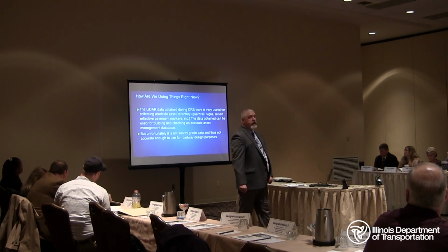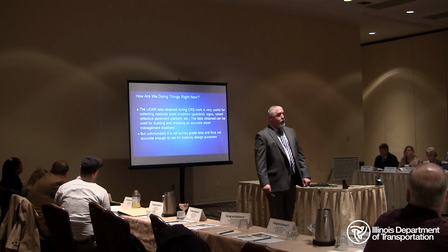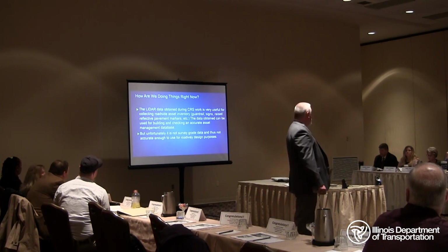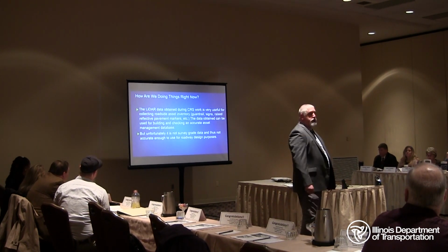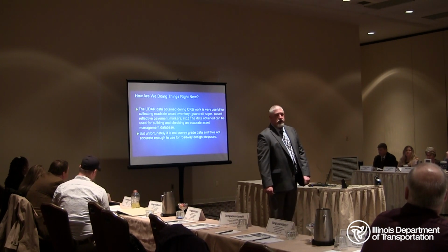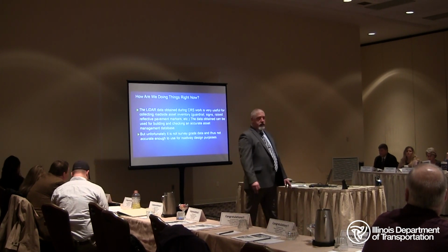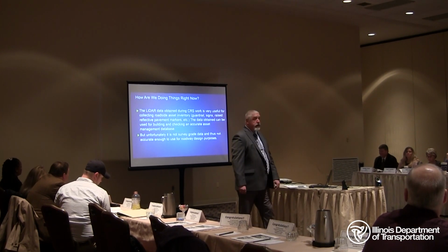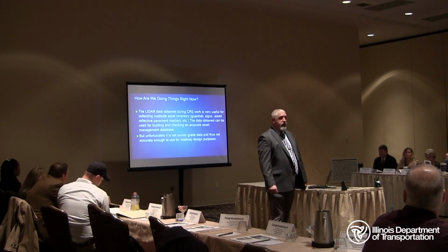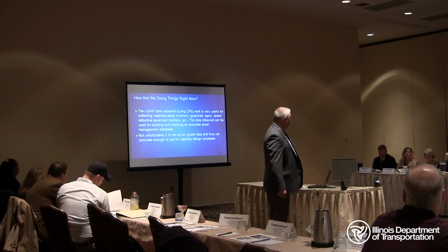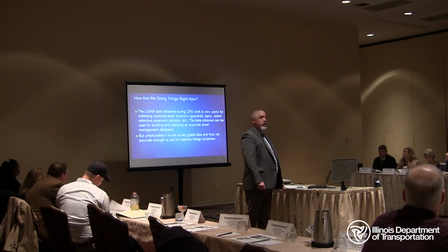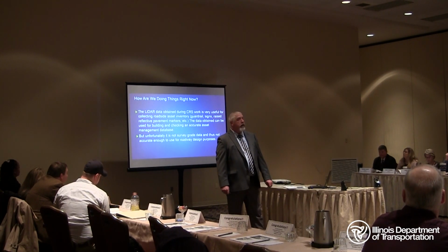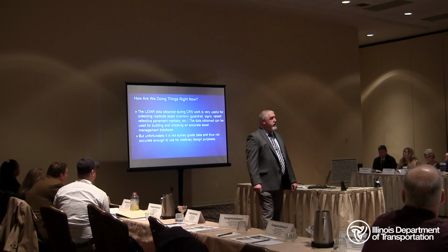Now, the LIDAR data that's being collected now is still very valuable, even though it's mapping grade. You know, it's being used to develop roadside inventory, such as guardrail, signs, pavement markers, what have you. And that could be used for building and maintaining an accurate asset management database. But like I said, unfortunately, it is not survey grade, and therefore can't be used for design survey work.